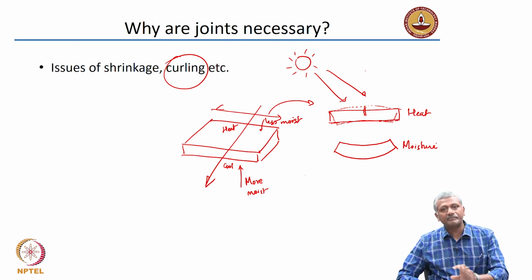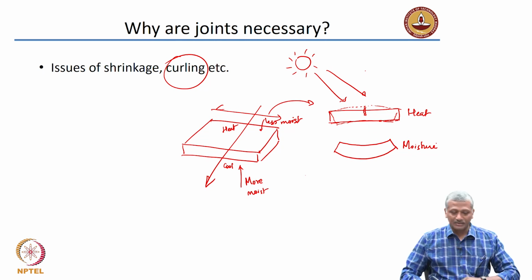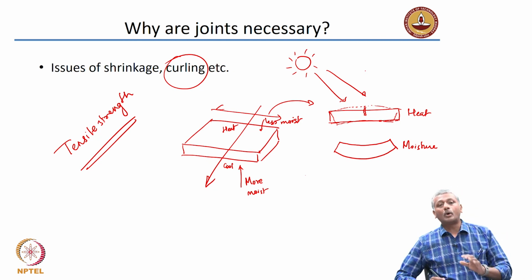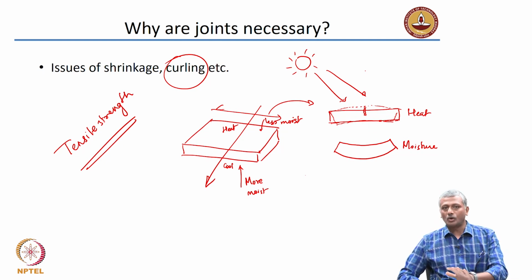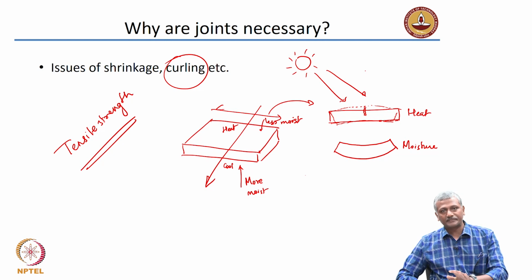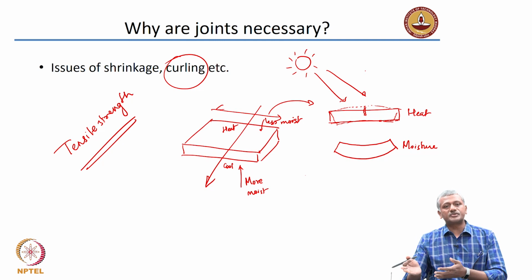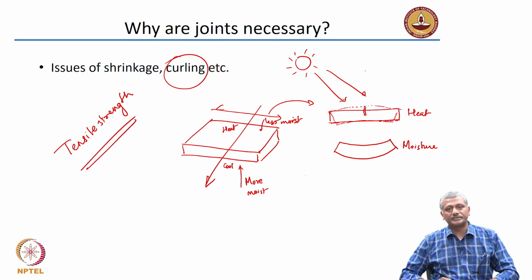about cement concrete pavements, it is no longer the compressive strength that is the deciding factor. The tensile strength is very important. The tensile strength is the property that you will be using to decide upon the suitability of a particular concrete type for use as a pavement slab. Okay? It is no longer the compressive strength, but the tensile strength. Of course, we saw earlier in the concrete chapter that usually tensile strength is related to compressive strength. The higher the compressive strength, the higher the tensile strength.